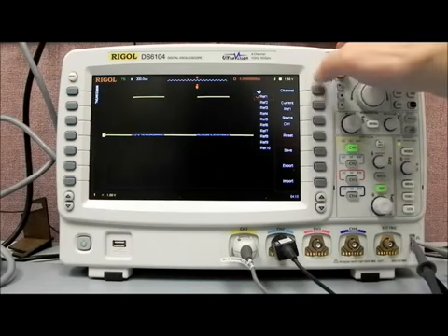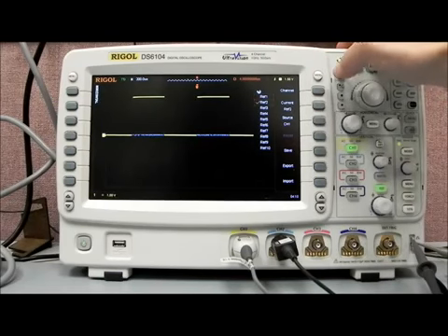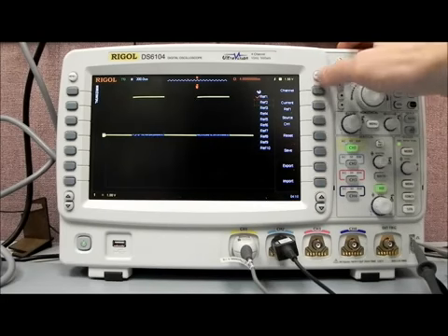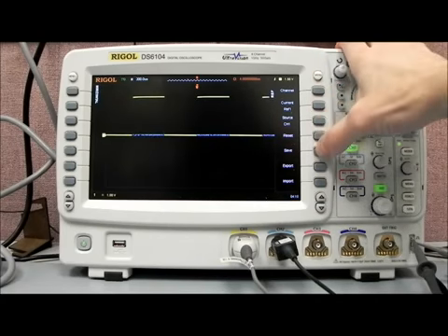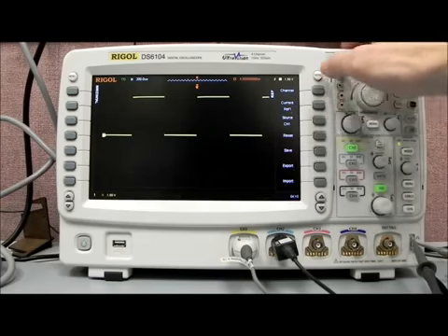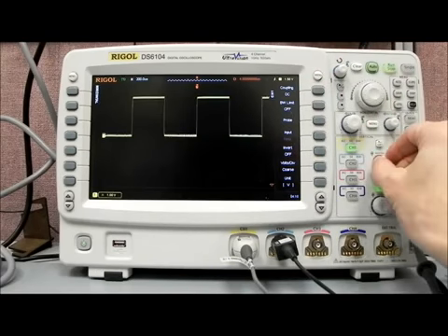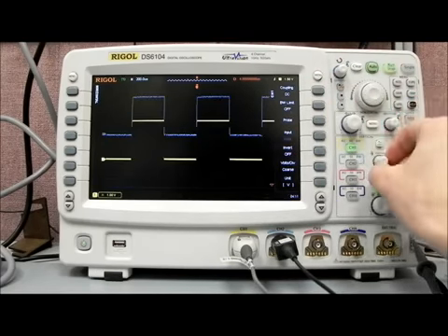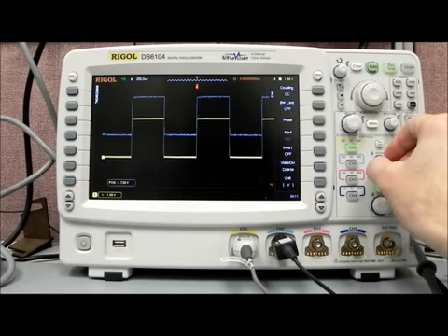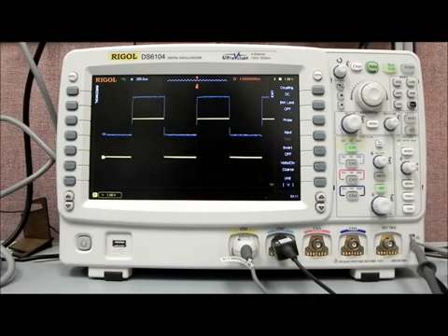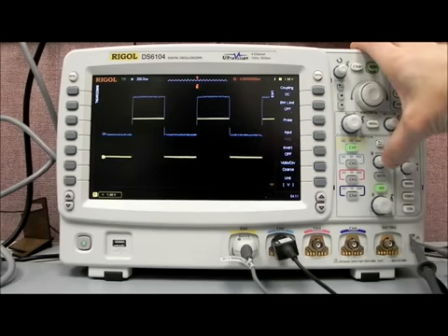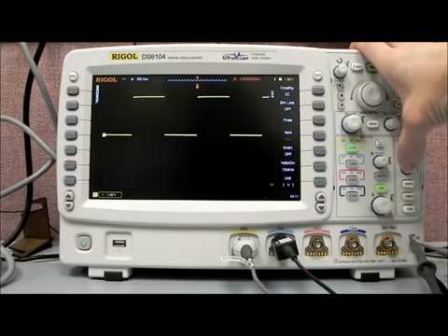So let's save this for reference channel 1. Oops, I'm sorry. A little overzealous with my pressing. And then let's do a save, and you'll see now if we move channel 1 that we've saved that reference waveform. And reference waveforms can be very useful if you want to maneuver or manipulate a waveform and check it versus an original waveform. Just visually be able to take a closer look at how things are going with a particular waveform as you go through.